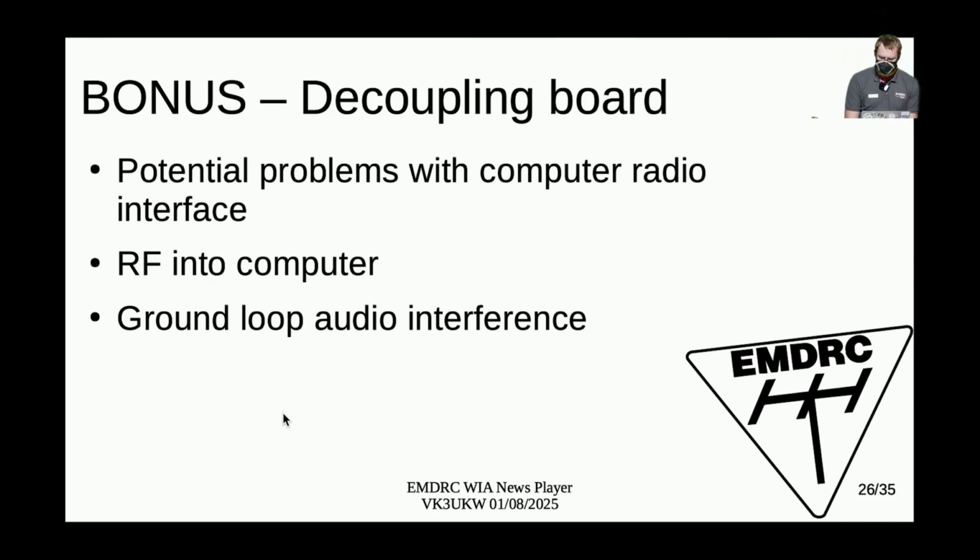we've got time. So the potential problems if you send analog audio into a radio are, firstly, the thing that everybody who runs 100 watts or more into FT8 to get their digital DX experiences: you get RF into the computer, because the RF comes back if you have an unbalanced transmission line and you don't have just the right chokes.